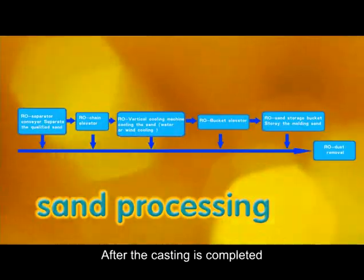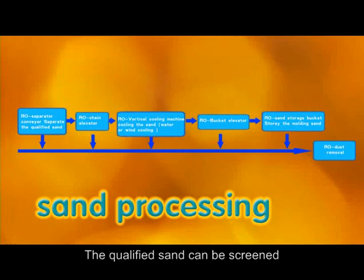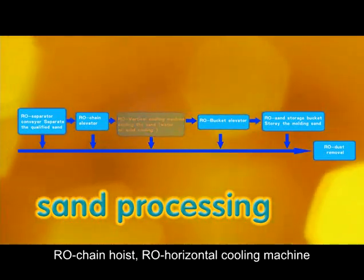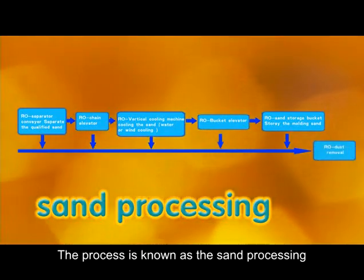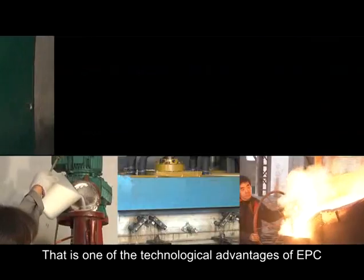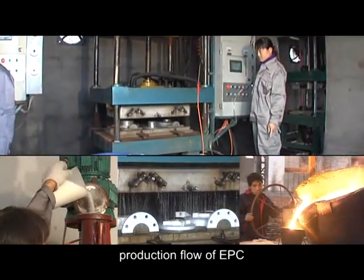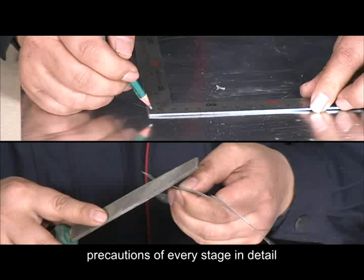After the casting is completed, we need to turn over the molding flask. The qualified sand can be screened from the used sand by sieving conveyor, chain hoist, horizontal cooling machine, bucket elevators, and other machines. The process is known as sand processing. The qualified sand which has been dealt with can be used circularly. In this way, we can reduce the cost of investment. That is one of the technological advantages of EPC. The presentation above is the general production flow of EPC. Now we introduce the production flow and the precautions of every stage in detail.